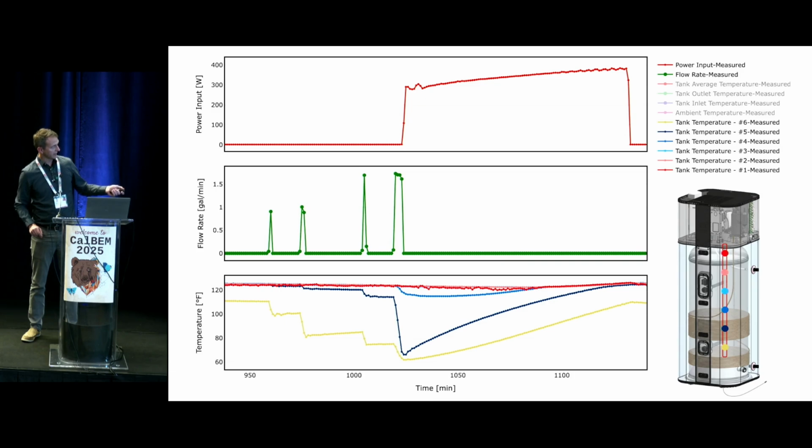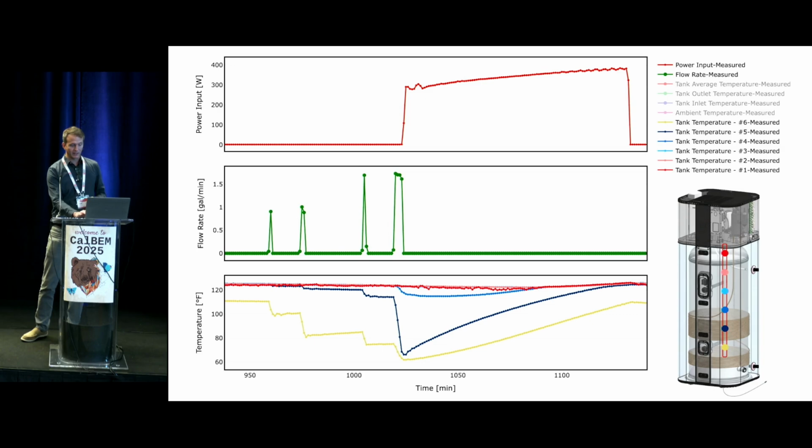and eventually getting to higher thermocouples in the tank. And at some point, there's a thermostat that triggers the compressor to turn on, and you can see the temperature inside the tank increase until the compressor turns off again. So hopefully that makes sense.